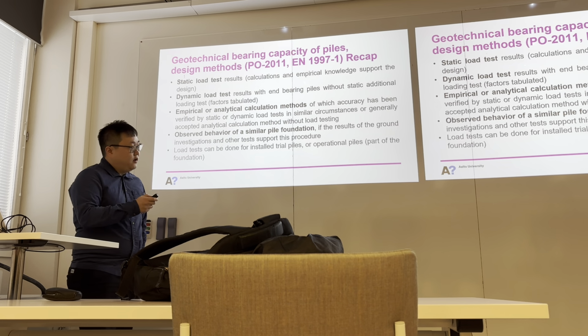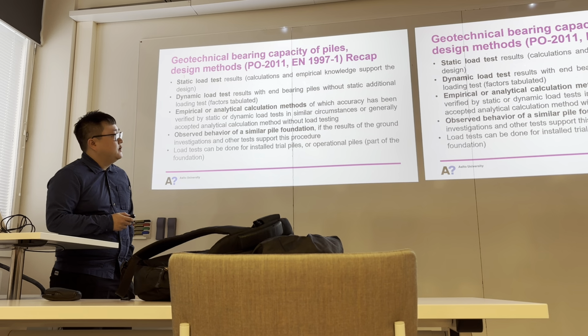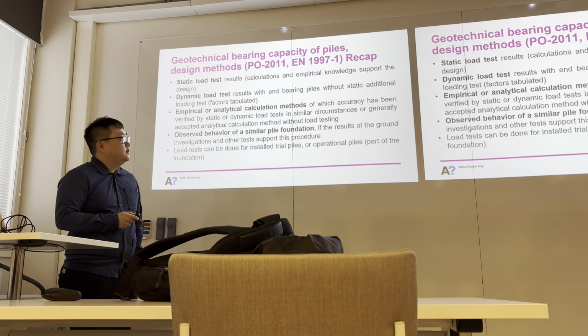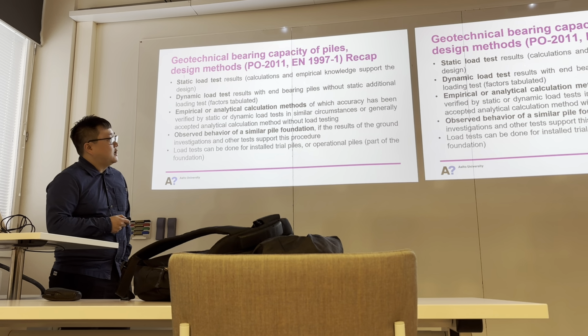For the design methods of the geotechnical bearing capacity of piles, according to the Eurocode, generally we use 4 different methods. The first one is the static load test. If we have the results of this, the calculations and empirical knowledge can support the design.